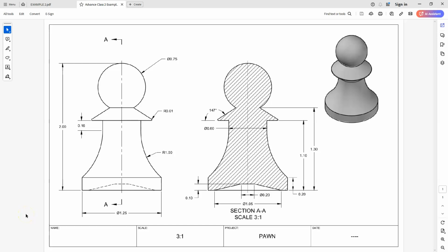And in this one we're going to be creating this part in 3D using Inventor. Now this is a cylindrical part, so that's kind of your precursor to know which command we're going to use. So if you're looking at cylindrical parts, just remember that. Think of whatever you're creating here as a revolve. And like I always say, when you're creating a revolve, think about creating half of a half. That's all you're going to need to create that full revolve. So let's jump over to Inventor and get started.